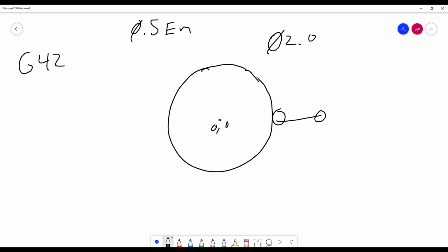G42, okay, X 1.0. It's 1 inch from here. We're going to comp to the right. The lead-in amount, our previous X and Y, wherever this is going to be, would be X 2.0. So the lead-in amount is 1 inch in this case. Plenty of room. Okay? So we're right here. That would be a G1.